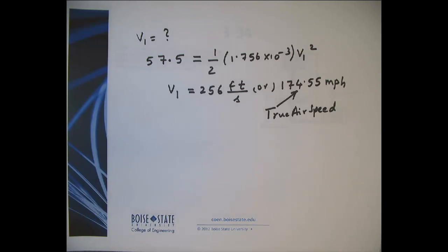Okay, so till now all we had to use was one equation, which was the Bernoulli equation along a streamline. We also learned that in some situations we might have to use another equation which we learned in class, which is the conservation of mass. For a steady flow, you know that Q equals area times velocity, the flow rate. So if you have steady flow at 2 points, 1 and 2, Q1 should be equal to Q2. So let's look at a problem where we might have to use that in the future, but I'm just telling you that in some instances we have to use that.